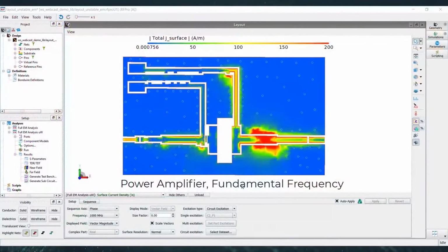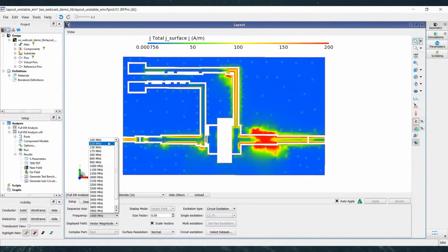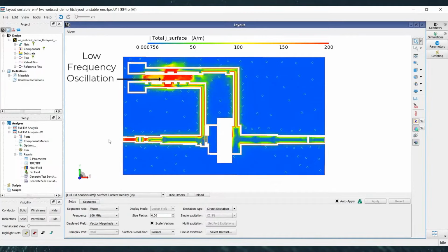Well, there's all kinds. Certainly oscillations and instability in circuit design would keep you up at night. One thing a lot of people don't realize is you can have a perfectly stable circuit in a 50 ohm system, but then if you stick an antenna on it, say you're designing at 1 gigahertz and the antenna is tuned for 1 gigahertz, so you're good, you don't have to worry about that, right? Until you start thinking about the other frequencies, and you ask what the antenna does at 100 megahertz or 50 megahertz, and you realize it's really reflective.